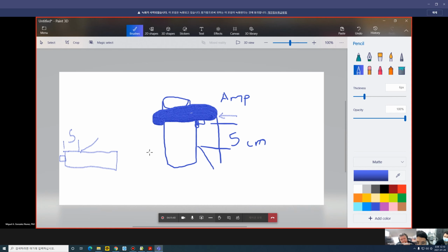So, in real tests, if the sensitivity of sensors is lower than the reference, we should fix something, right? Yes, try to decrease the thickness, in this case of the wax that you are using.